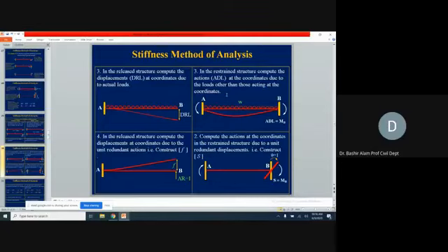So that is why it is clearly written that whatever corresponds to the unknown joint displacements, you exclude from the ADL matrix. Where do we include them? We include them in the AD matrix. So here, at this location in the clockwise direction, we were having our D value, the unknown joint displacement. This is the corresponding fixed end action, which is MB, and that MB value will be equal to ADL.